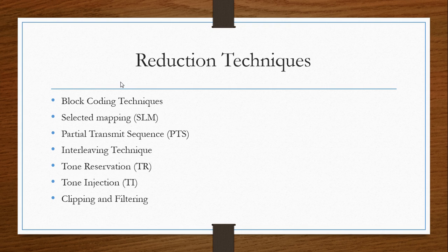We have a number of reduction techniques like block coding techniques, selected mapping, partial transmit sequence, interleaving technique, tone reservation, tone injection, clipping, and filtering. So let me go through some of the reduction techniques to better understand the concept.